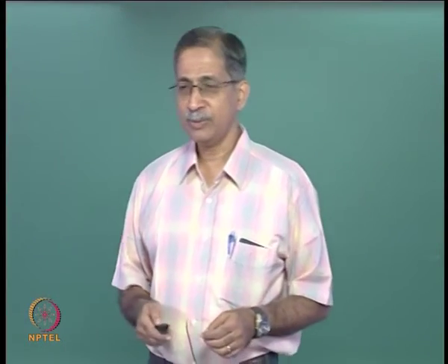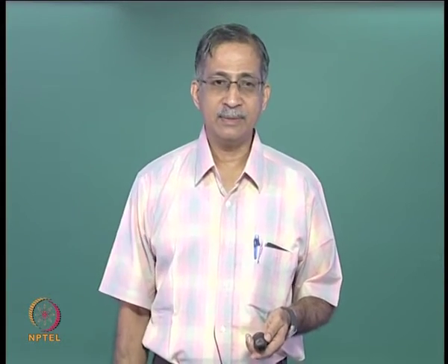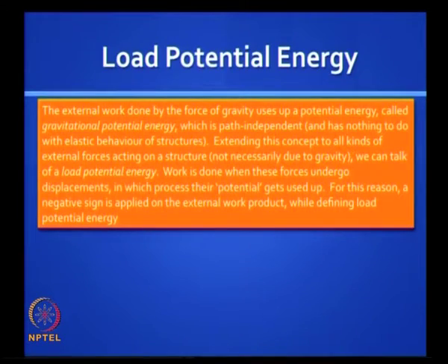We now come to energy methods proper, and there is a term invoked in energy methods called load potential energy, and it is a concept which you need to understand. It is given here: the external work done by the force of gravity uses up a potential energy called gravitational potential energy, which is path independent and has nothing to do with the elastic behavior of structures.